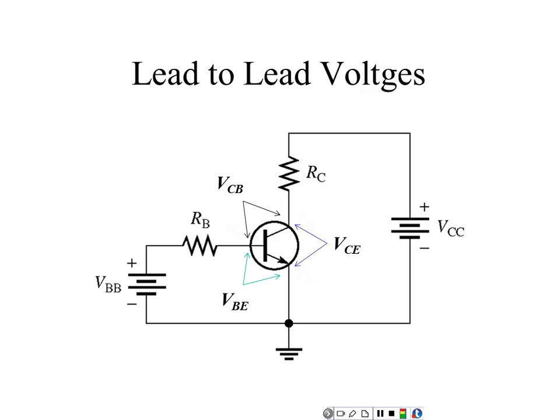But they'll say the other lead is open. So if you got one lead open, the transistor is definitely cut off. So what we're trying to do is see what will break it over when the transistor's cut off. And that's going to be in all your bipolar transistor data sheets. You can break over between three leads.